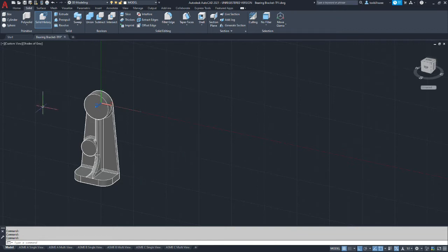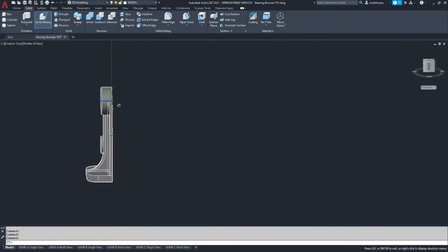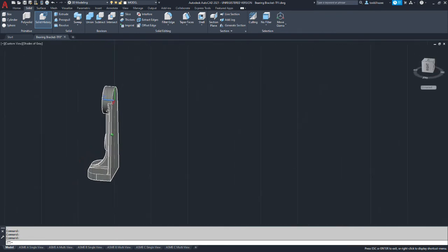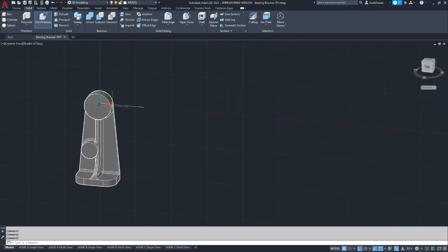Okay. If you've been working, make sure you save before you do the mirror. It can be a processor intensive action. Sometimes it is not. Okay, so I'm currently set up with my Y and X plane, and I intentionally drew my model right on that plane, so that way I can use it to mirror the part. So I'm going to be using this XY plane as my mirror plane.